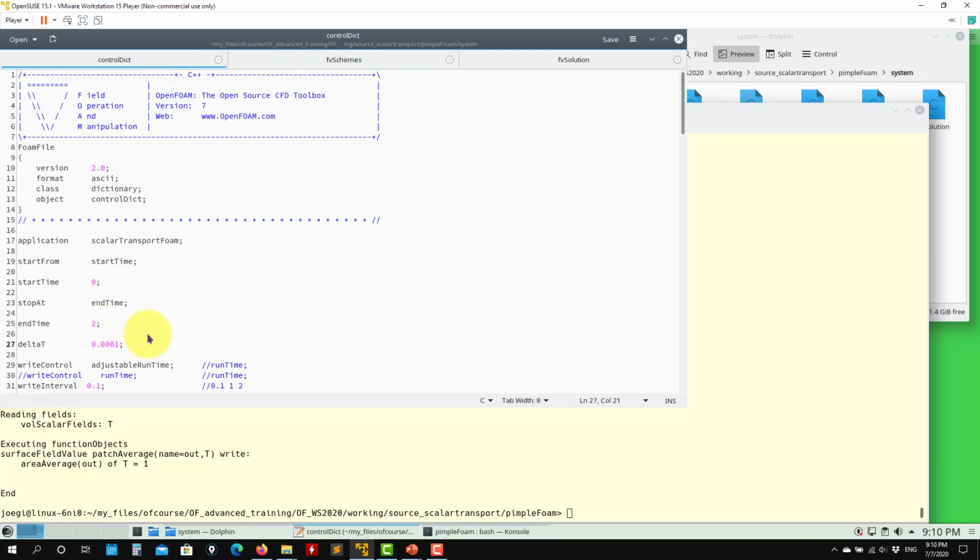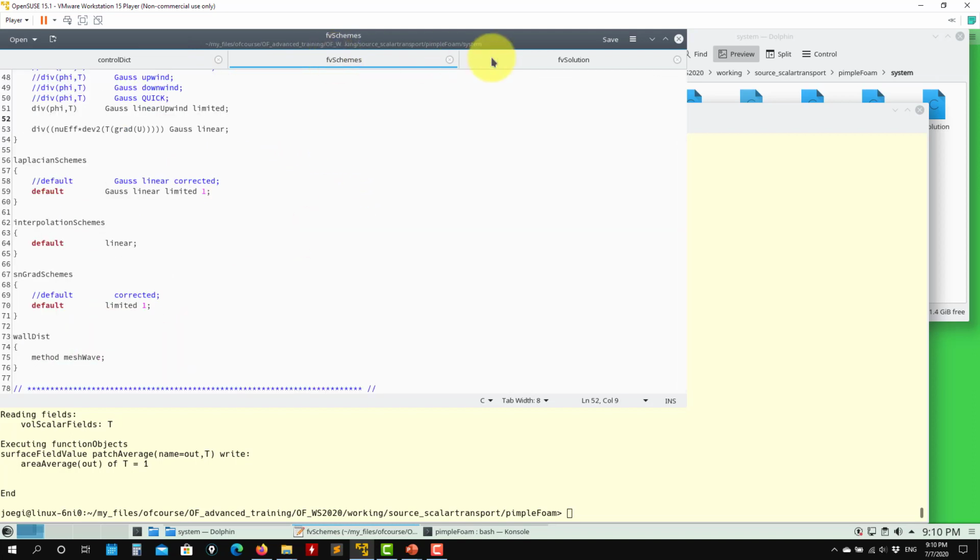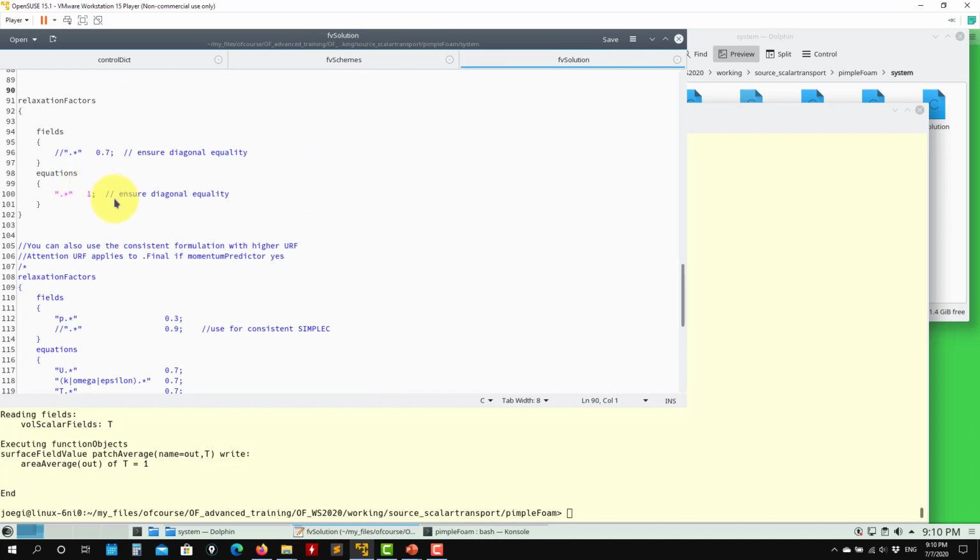The most important one is the time step. Okay, a small time step means good accuracy and a stable solution, and then there is this one. So even if you put this one large, the time step is the one that will improve everything. Okay, but usually my advice is to use the same values that you have as the industry standard, or if you want to use other values, instead of 1 use something large, 0.9 or 0.7, which is my default value most of the time.